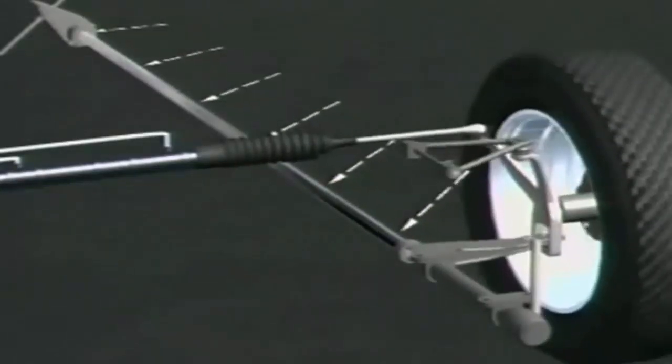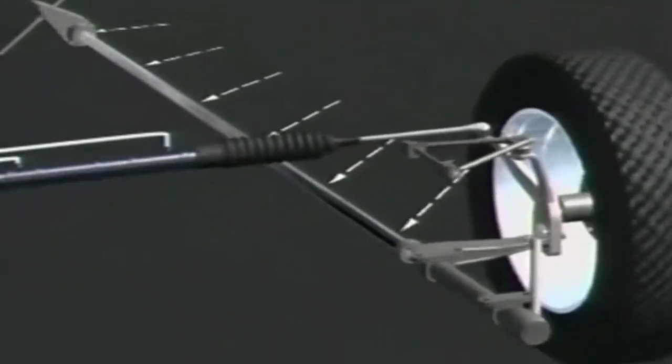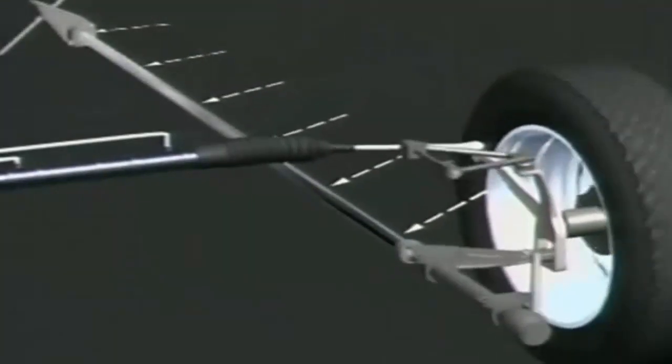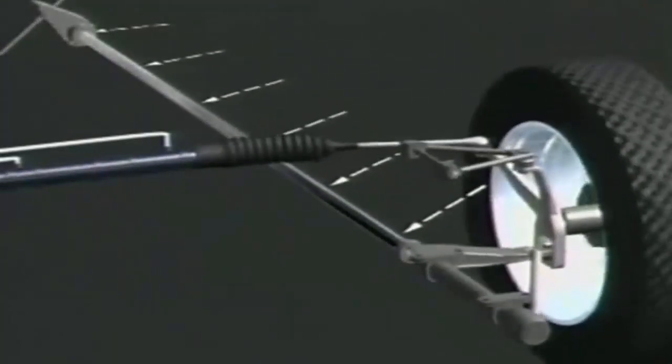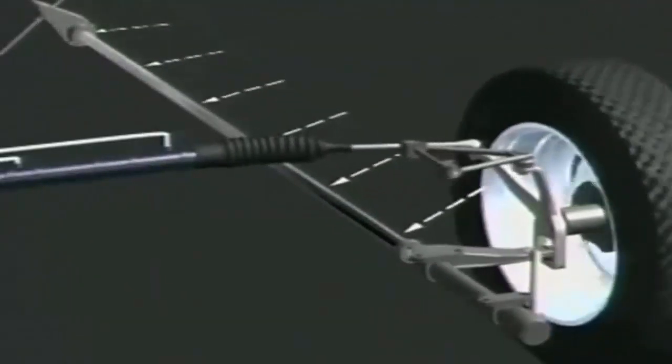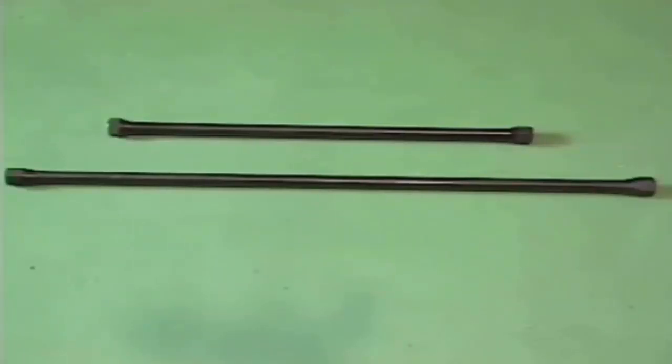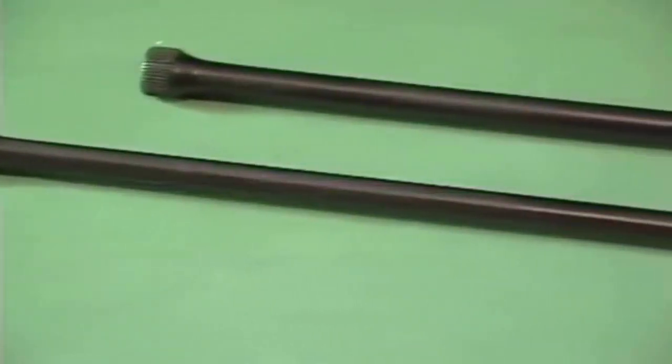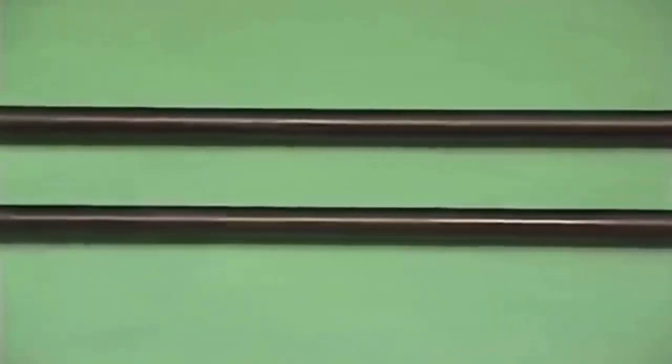When the vehicle is placed on the road, with the control arm connected to the suspension assembly, the bar supports the vehicle load and twists around its center to provide the springing action. Spring rate depends on the length of the bar and its diameter. The shorter and thicker the bar, the stiffer its spring rate.